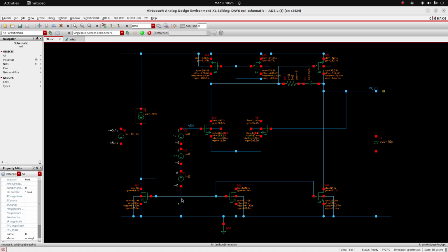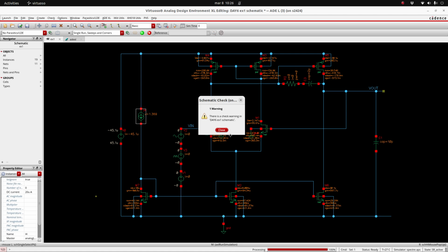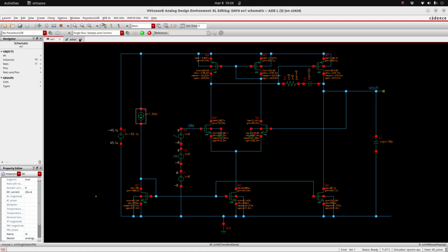So now I'm going to just double the biasing current, so we will have 10 microamps for the differential pair and 60 microamps driving the output. So in principle that will double the slew rate of my amplifier. Yeah, I can play a little bit with how much current comes to the input and the output, but for now we are just going to double the biasing current here.